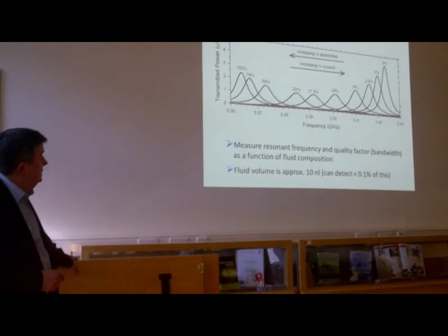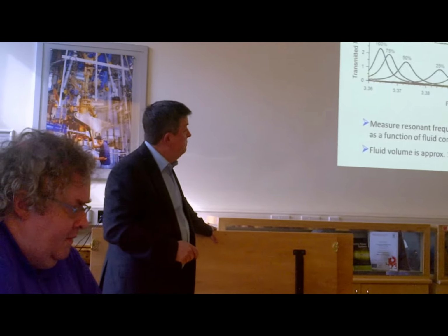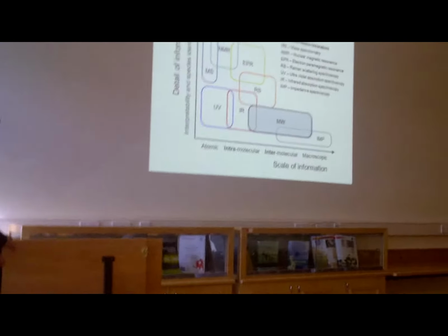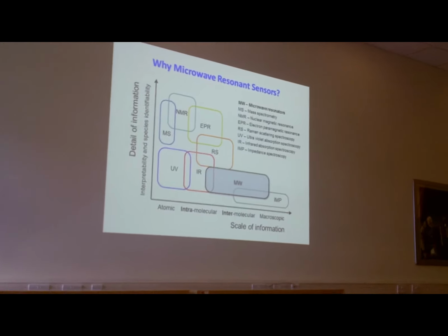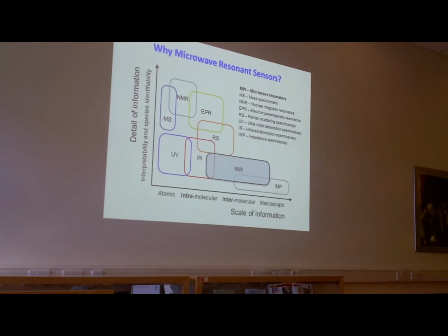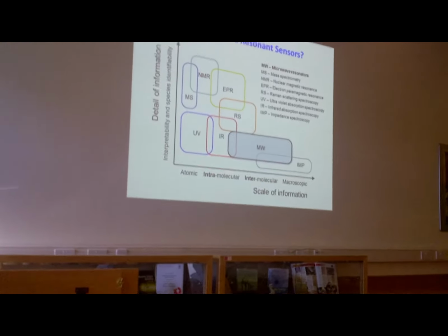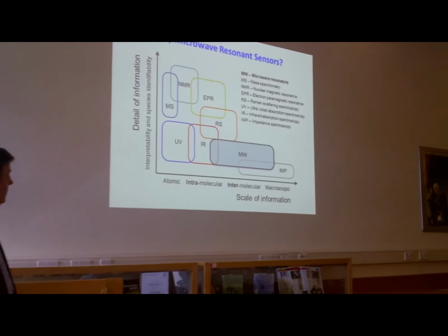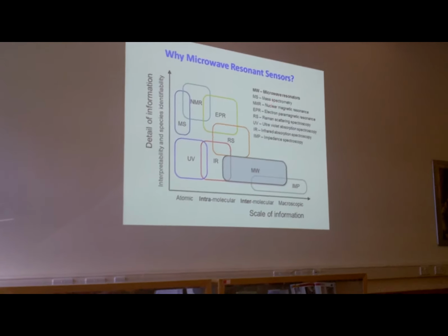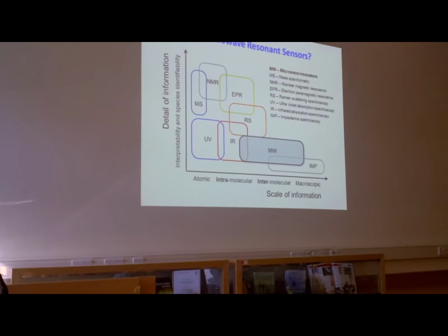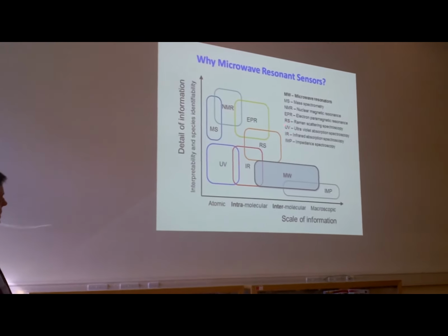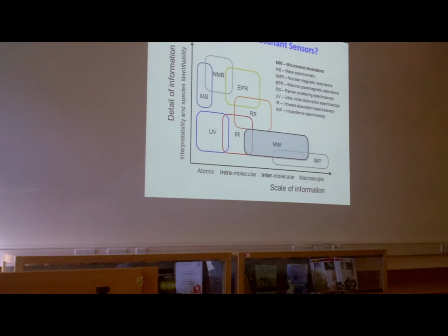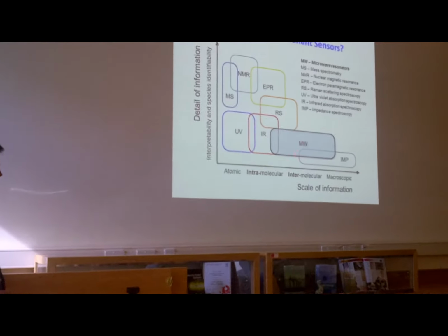You notice there's a continuous variation of frequency shift here as you go from 0% one phase to 100% the other phase. You also notice there's a dip in this, which I can't explain, but maybe I'll leave that one until the end. Okay? But you can use this clearly as a detector. In this case, for example, of a system that involves acetonitrile in toluene. So it could be looking for water in the materials as another thing. You know, it's very sensitive to water, this. Water being a massive absorber of microwaves at these frequencies.